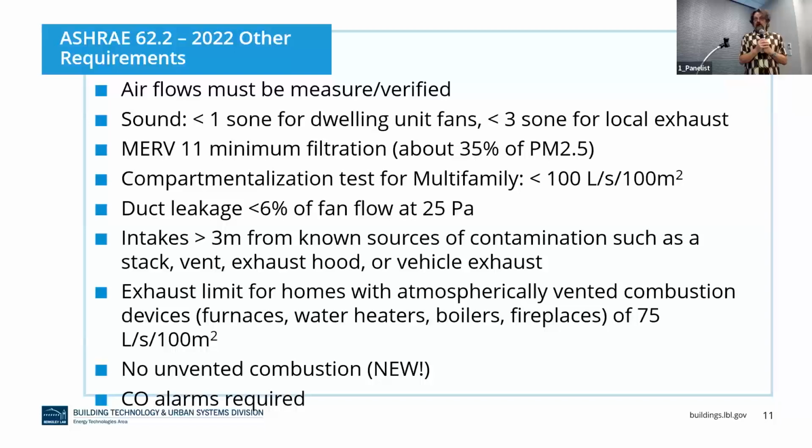Something that might be more relevant to multifamily construction is we have some special requirements for multifamily buildings. We have this thing called compartmentalization, which is the leakage of the interior partitions rather than the exterior envelope, where we're trying to limit transport of contaminants and air from unit to unit. So we have some requirements for that. Odd things about, we don't want leaky ducts. We don't want to recapture from an exhaust for our inlet. So we have ways of separating those and so on.